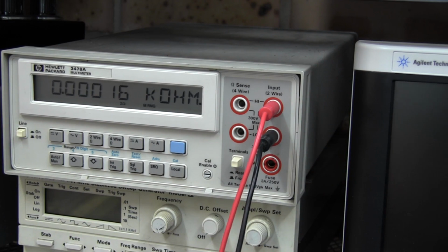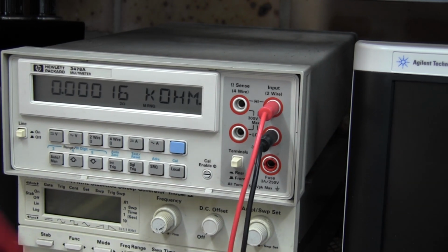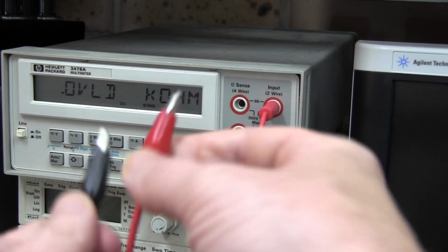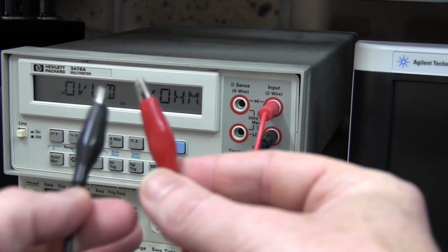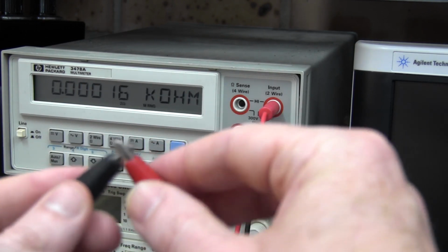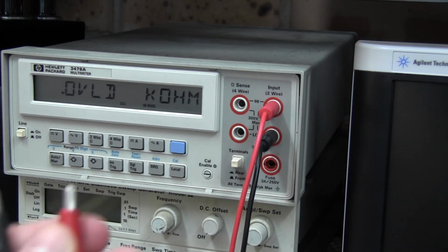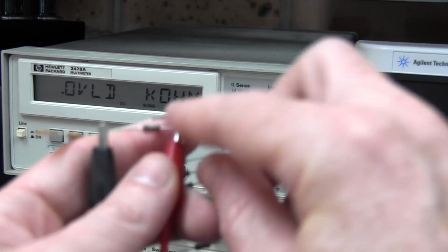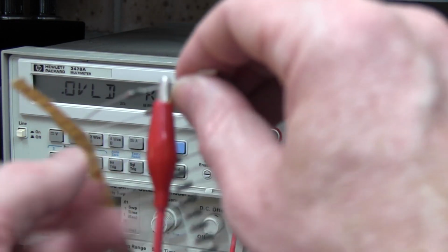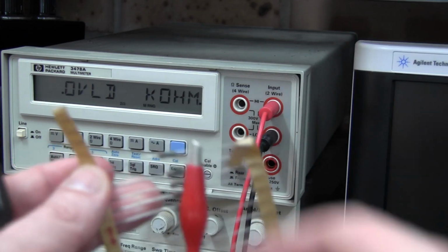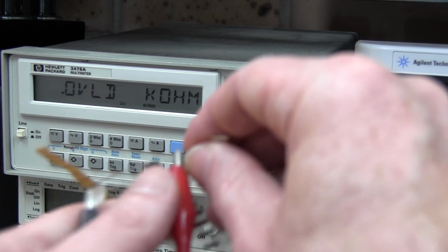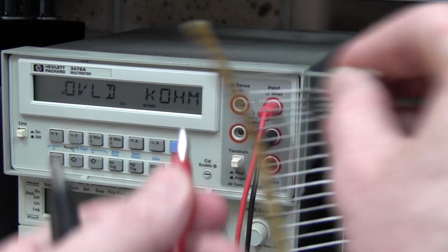And of course, the other thing you have to consider is the repeatability of your probing system. Now, in this case, we've just got these regular 4mm banana plug to alligator clip leads, fairly cheap ones, but they should do a fairly decent job of actually biting through any oxidization on the leads, and because we've got 1K, it's not going to be a huge differential. If we were measuring a 100 ohm resistor or something, it might matter, or a 10 ohm resistor would be worse. Then the contact resistance could vary a bit, but on 1K, it's pretty good.